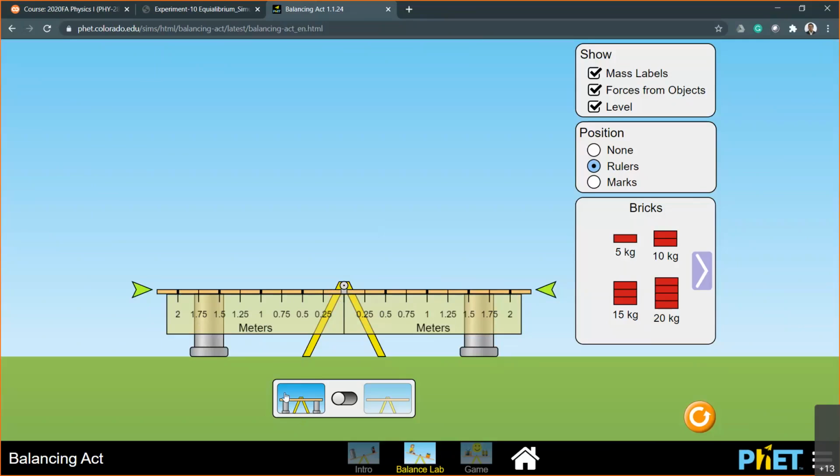And you can see below here, there are 2 options right now. Left hand side option, click. Then you can see these 2 gray colored cylinders on there. And if you click the right hand option right here, then you can see the 2 gray cylinders will disappear. Okay? Click on that because we don't need the gray cylinders to hold the object.